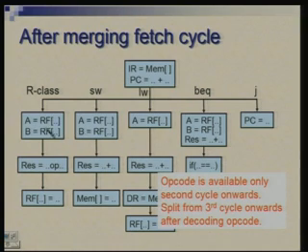One thing is that not all instructions are trying to read 2 values from the register file. Here you need 2 values, here you are reading 2 values, here you are reading none. Is there any harm if all instructions read 2 values? They may use it or may not use it. The answer is there is no harm. It does not cause any problem in the functionality of the instruction.